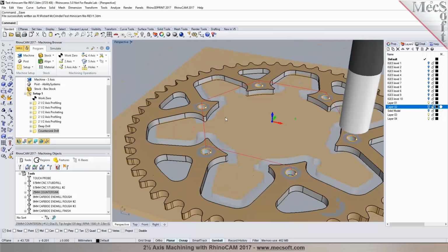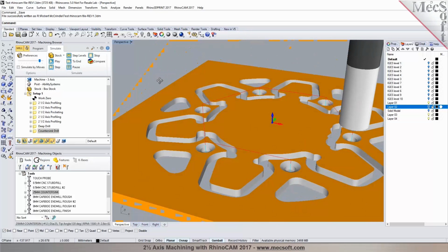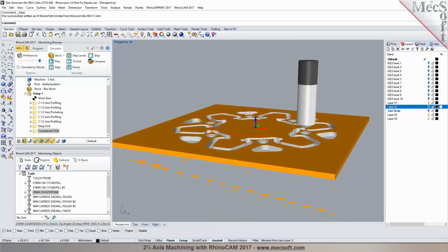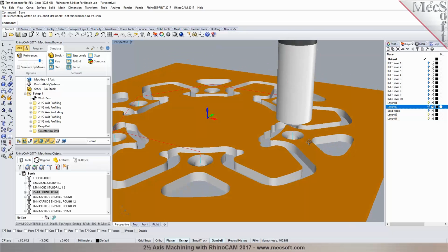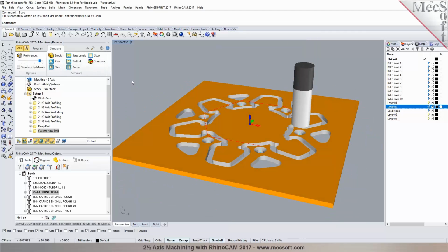Yeah, I understand that, but as you would draw that in Rhino 3D, you draw it as a chamfer. So is there any way of assigning that tool that you just picked to that chamfer so that it automatically recognizes that that tool needs to do that part of the job? Yeah, you could. Such as the same with the drill for the holes.